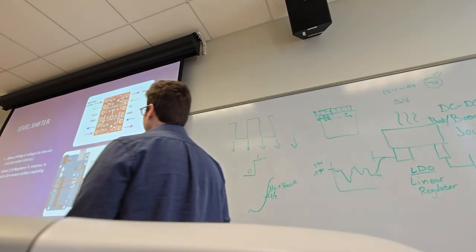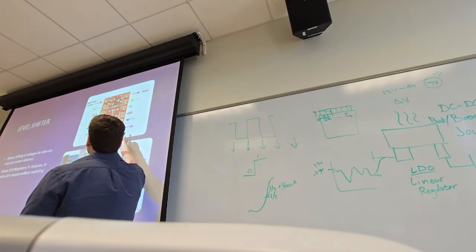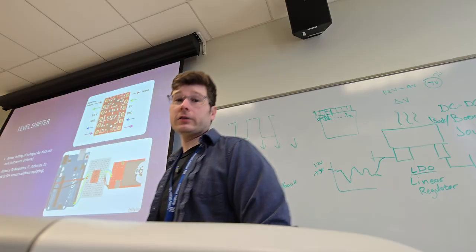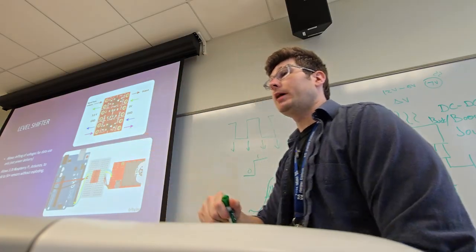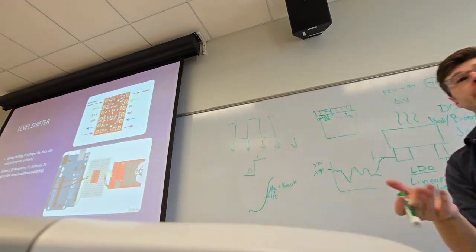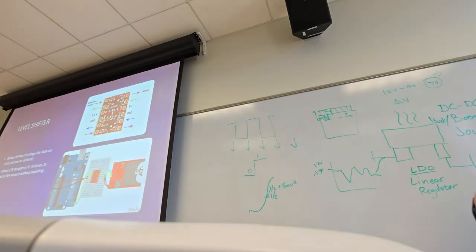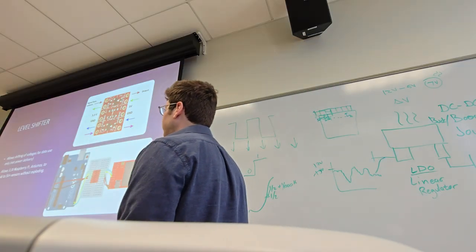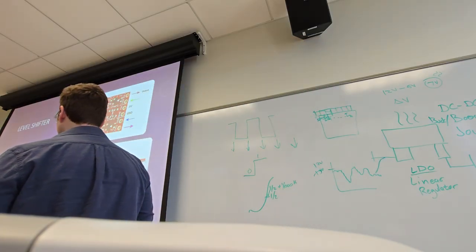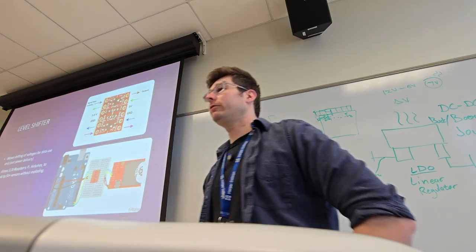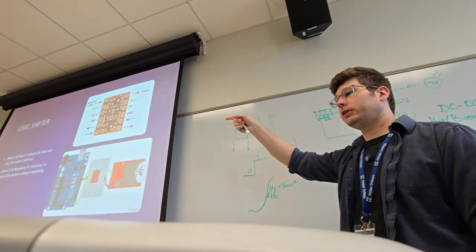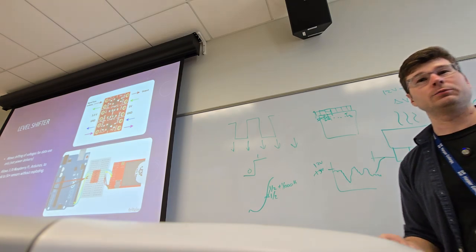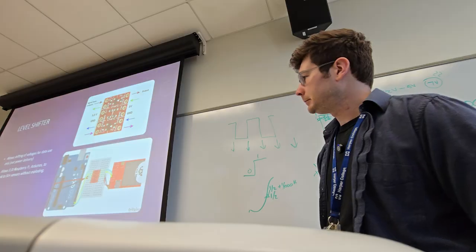Okay, but so in the future, I'm probably going to get these, and so I'll probably get one of these Arduino sensor packs, a few of these level shifters, and then make some 12 volt sensors to use for PLCs. Or in the future, if you guys were tasked with such a thing, you wanted to avoid using an Arduino altogether, you had a sensor that talked 5 volts and you wanted to wire it into a PLC that only understood 10 or 12, you would use one of these, right? You would use one of these to bridge the gap to get it talking 10 volts, 12 volts, whatever, and then proceed accordingly, okay?